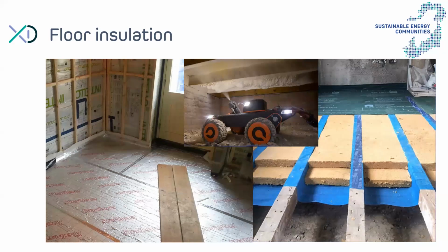The typical way of doing that is to put a mesh or a membrane between the joists. Lay the insulation boards between the joists, supported by that membrane, and then apply another membrane over it that prevents moisture from migrating into the insulation layer and also acts as an airtightness layer. Then seal that membrane around the walls, and that would do a super job. Even better, you could consider adding underfloor heating in those situations, which would be an ideal combination with an air source heat pump, but that's a different discussion.